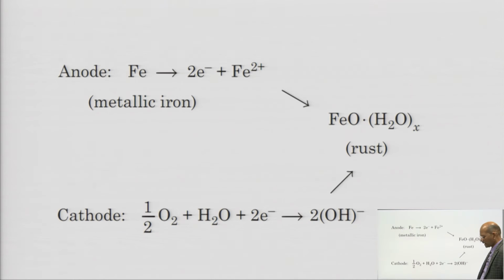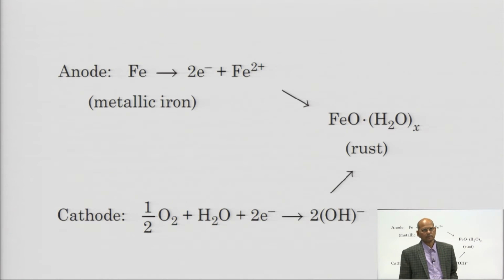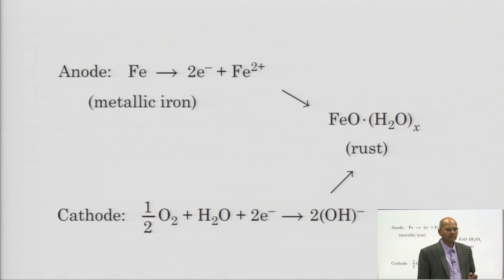So, what is the problem with this iron oxide? The volume of rust is much higher than the original volume. Generally it ranges from 2 to 6 times, and sometimes more than 6 times, the volume of the original material. The volume of the iron oxide is very high, so that is going to exert pressure.